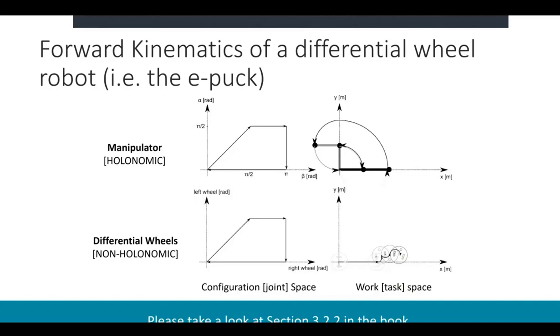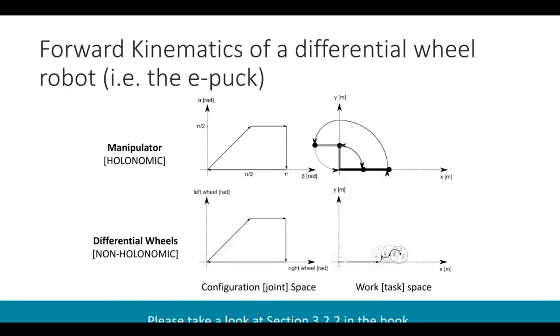So if something is non-holonomic, that's going to mean that we have to take some extra care to figure out where we are. Again, because our joint angles don't tell the full story of where we're at, right? It's joint angles over time that do that for us.